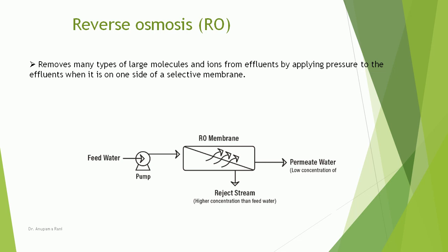The film contains microscopic openings that allow water molecules to pass through but retain dissolved solids by either molecular sieving or by some other mechanism which is not yet completely understood. The process results in a concentrated solution of the ions on the pressured side of the membrane and product water relatively free of ions on the other side of the membrane.